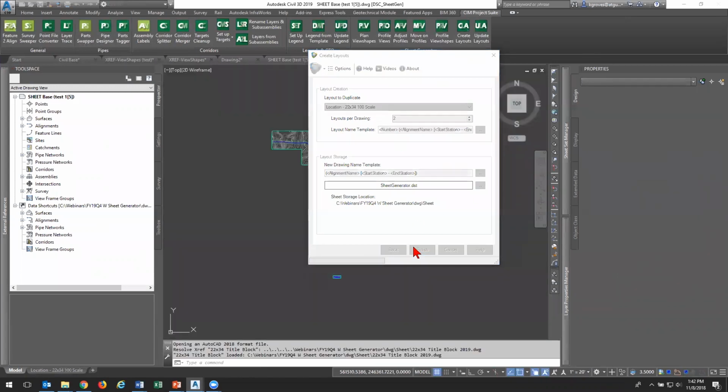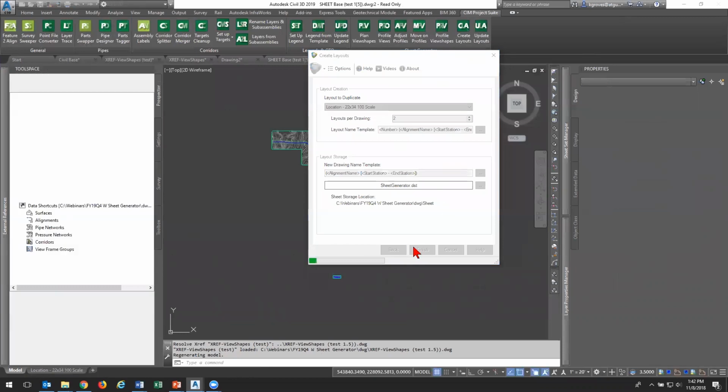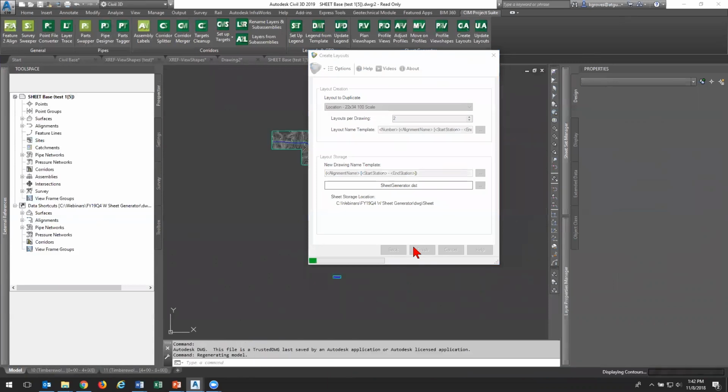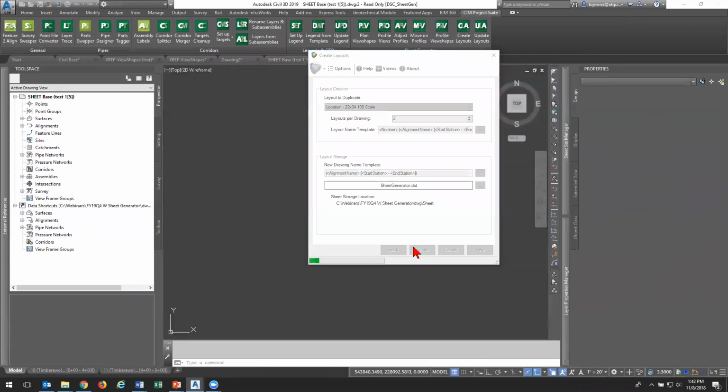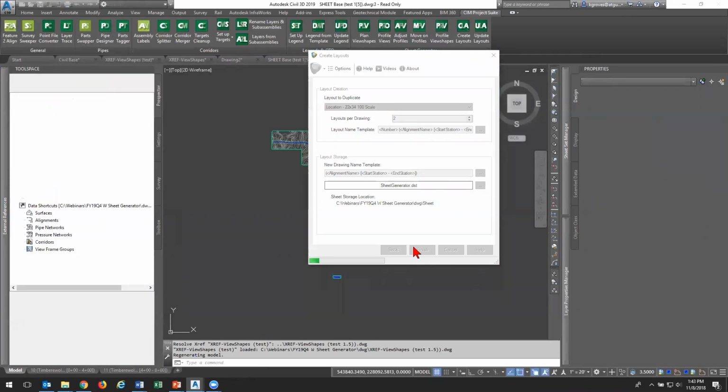So with this again, we are just creating some polylines and some blocks, or rather, the tool is. It's creating polylines and blocks, and this is information that's being shared across my XRefs. I don't have to have everything live in the same drawing. Also, we want to make sure that we don't have the original copy of our objects in the drawing we're going to use to create the rest of these.